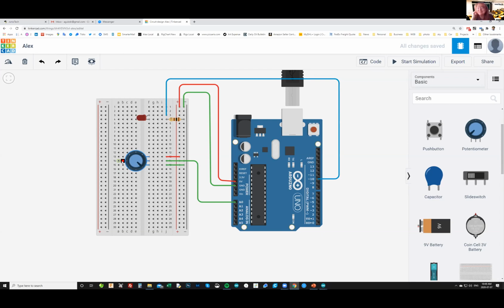Yeah, please do. There is pretty much only one way to use it: you put it standing across the gap on the breadboard. There is no other way. It will not go any other way. So it can only go with the 2 legs standing on one side of the breadboard and a single other leg on the other side of that gap.